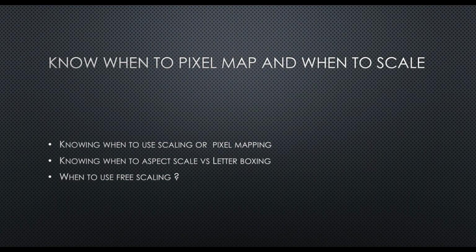If you were to take a 16:9 signal, a camera signal that's coming in, and then let's say they decided to make portrait screens on your stage, how would you scale that over? Take 16:9 video and scale it on a column of screen. It is going to be super hard to see anything on that, and we'll take a look at an example of that. You might want to use aspect scaling at that point, and then stretch that signal top to bottom fill, and then cut out everything left to right.